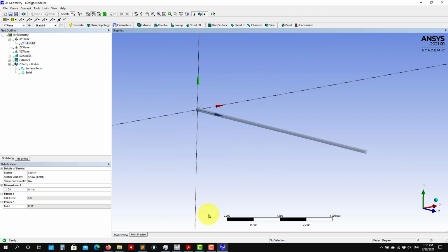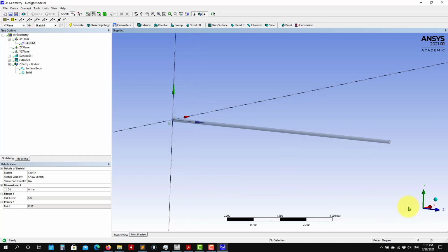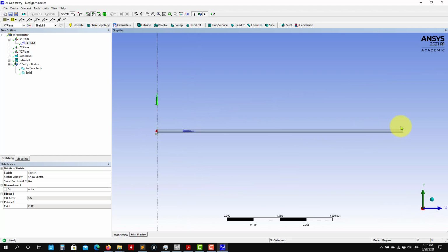Okay, but there is not only this way, there are many ways to do this. Just to show you another alternative. This one we were using extrude, this option. We can use also revolve. With revolve, we can create a section, a rectangular section, and revolve around an axis. So how to do that? I want to do another sketch.